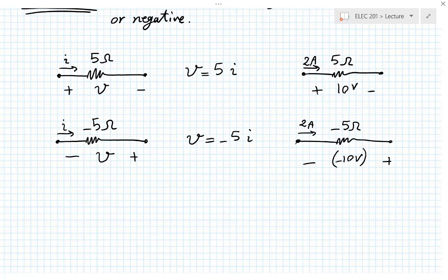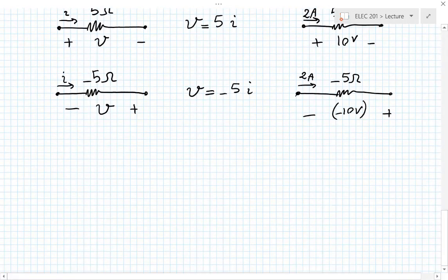So if I go back to the convention that we were talking about 10 minutes ago, right? If I say that my voltage is minus 10 volts, and the way I have defined the polarity, this side has the plus, and this side has the minus. Meaning, if V was a positive number, this side was higher than that side. But V is a negative number, so it really means that side is higher than this side. So this is completely equivalent to this. Okay?